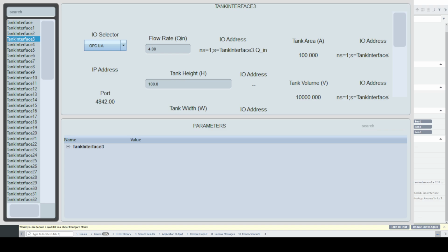So for OPC, I want to check whether OPC-UA is selected or not. From the address port marks, I can see over here this IO selector is giving a signal to this index value to set it to 2. Then when we set it to 2, this port is connected to the OPC-UA server, so the client can talk with this server.